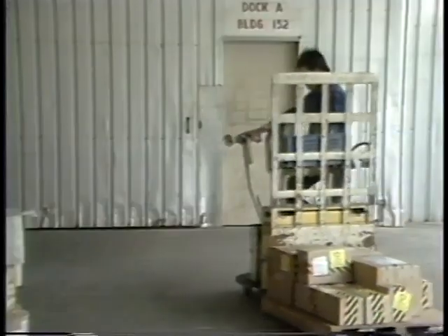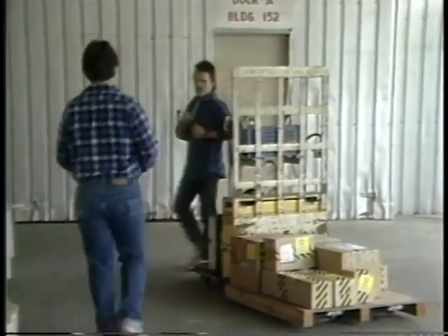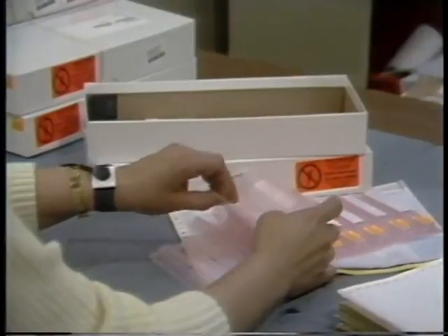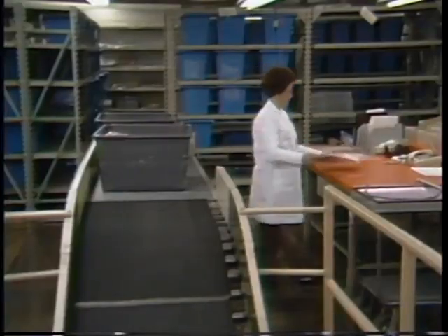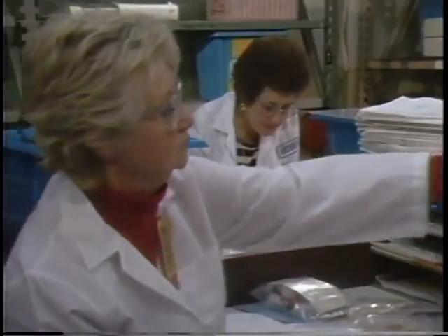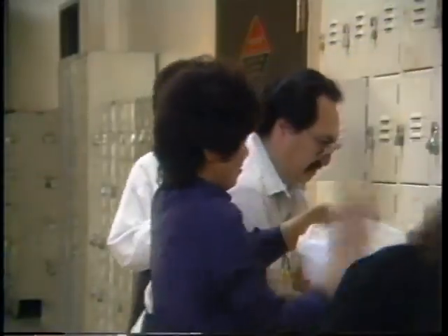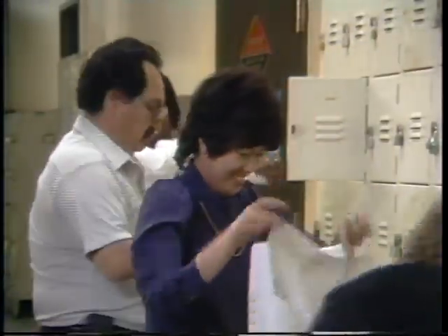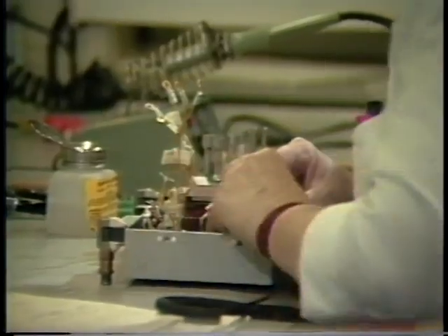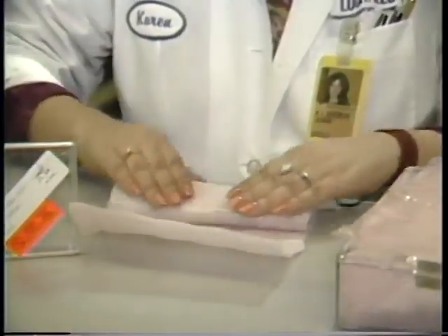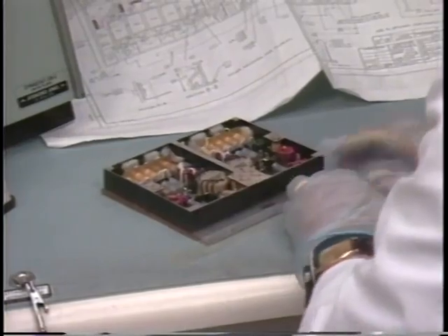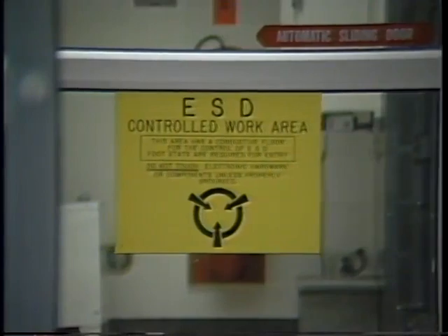Electrostatic discharge, or ESD, is simply the sudden transfer of stored-up static electricity from one surface or body to another. The threat of damage caused by ESD is great because of the number of hands a part passes through during production. If damage does occur, the results can be costly. One of the critical periods for a part is generally during manufacturing. More people handle a part during manufacturing than any other stage in the production process. That is why ESD protection must be built in.